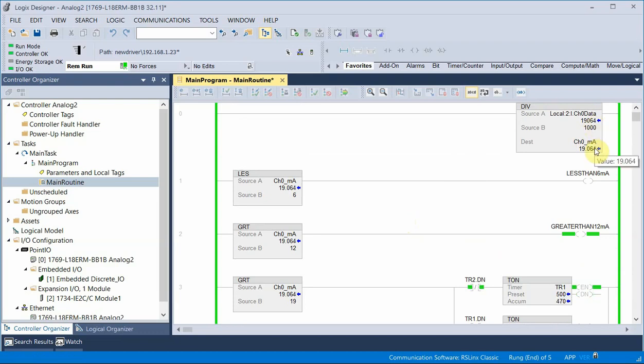If I want to turn that to, let's say I have tank level, 0 to 100%, what I would do is I would change the configuration at the card level, or I would just leave it at 4,000 to 20,000 and then come up with a compute instruction, just calculate based off of that number.